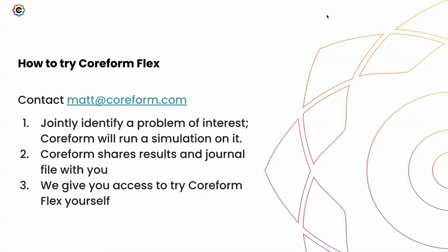There's another question about the materials available in Coreform Flex, whether there's nonlinear material properties available or composite material models available. Mike, if you want to answer that question. Yes. So currently, we're going to release in a couple of weeks some very simple neo-Hookean nonlinear materials. In the Q4 release, we'll have plastic materials and a few viscoelastic models as well. Our approach to material modeling has been to introduce some of the basic material models that you would want, and then we're adding the specific material models that our customers are asking for.